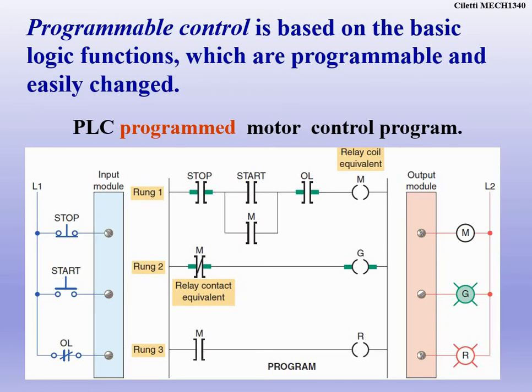We're going to learn later on that that's our seal-in logic. So when I hit the start button, I don't have to hold the start button. It'll automatically close itself and stay running until the stop button is hit. That's seal-in logic. I want you to think about that for later on. And then if we look at rung 2, it's normally closed. That's our motor contactor. So what's going to happen is, as long as the motor's running there, the green light's going to be going.